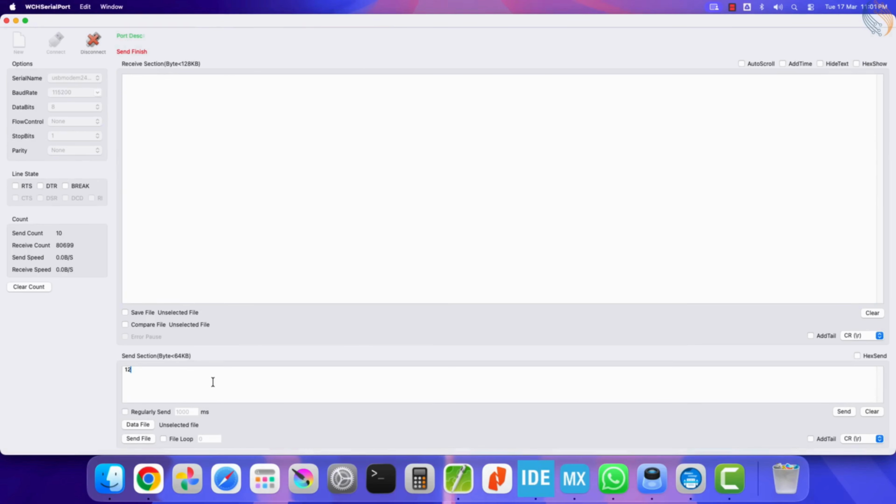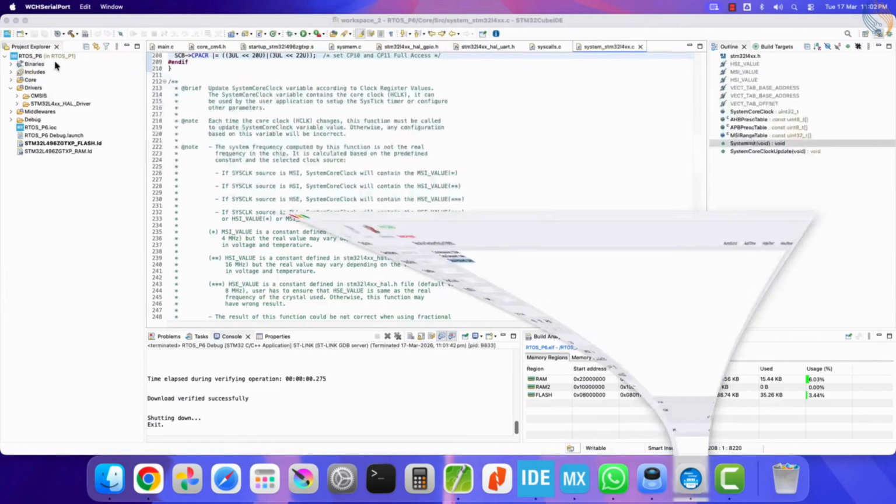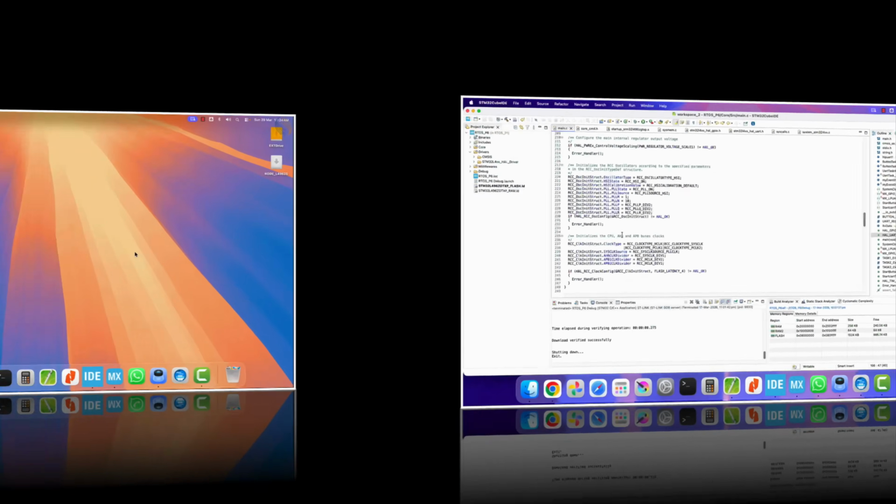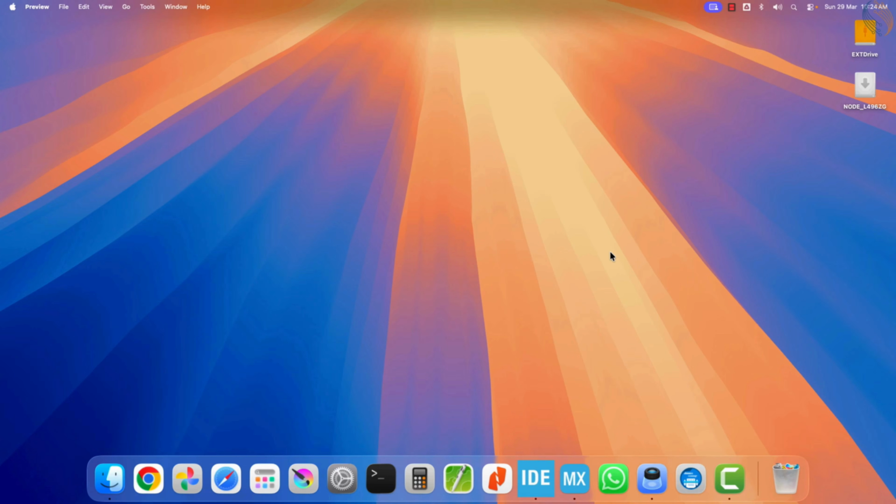Now let's test the UART event. I am going to send 5 bytes of data to the STM32 from the computer. And you can see the data has been printed on the serial console. So when the 5 bytes are received, the UART interrupt fires, the UART received flag is set, and the corresponding task wakes up and prints the data. So in this video we saw how to use event flags as a notification mechanism between tasks, and between interrupts and tasks. In this video, we are going to look at something a little different, software timers.